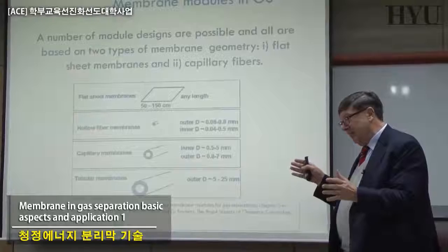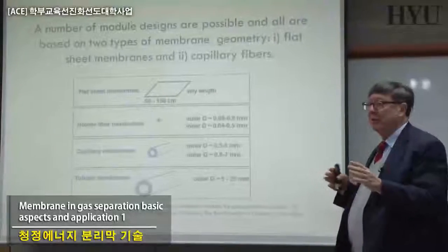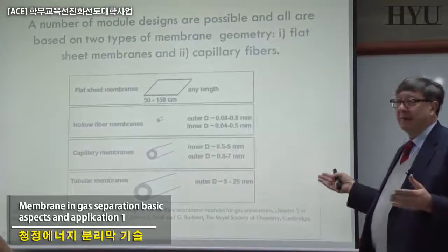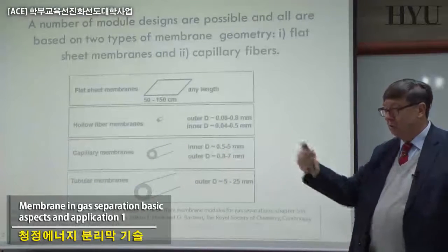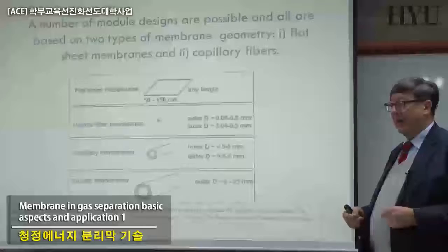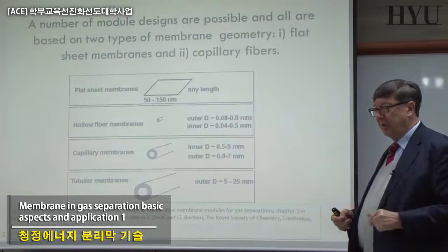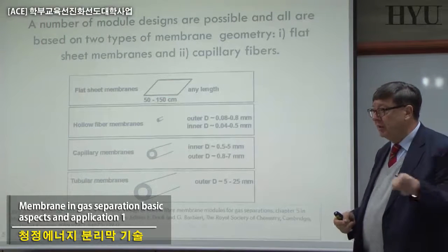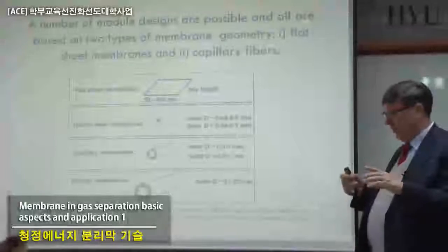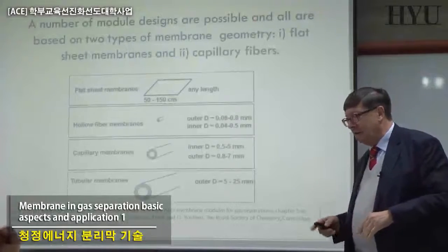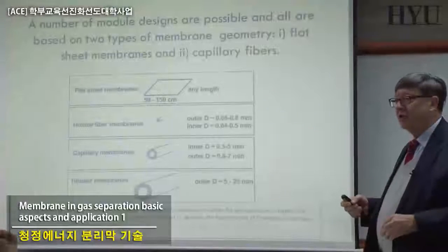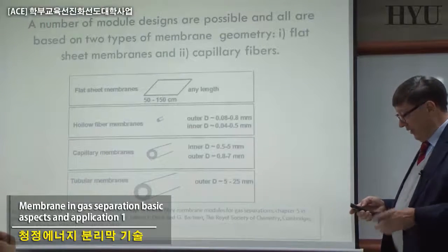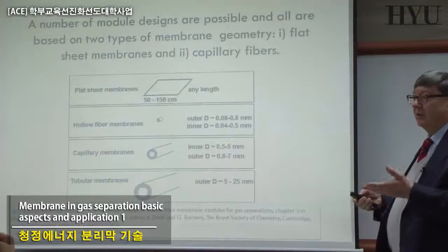All the modules, at best, are supposed to operate with the same basic parameters in terms of pressure drop along the module, difference in hydrostatic pressure on the membrane surface, and cross-flow velocity, in such a way as to control concentration polarization, etc. When you start to talk about gas separation, the engineering is a little bit more complicated, and I will just mention some of the problems.